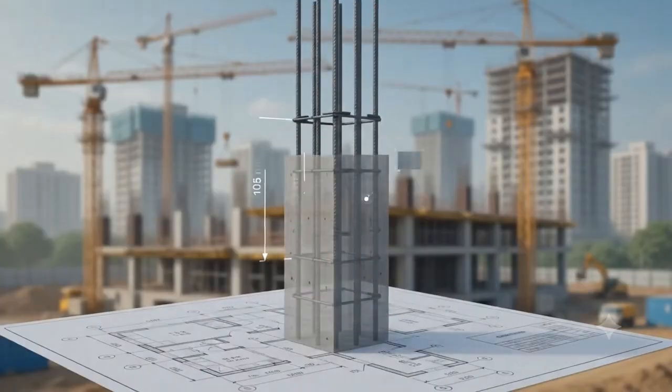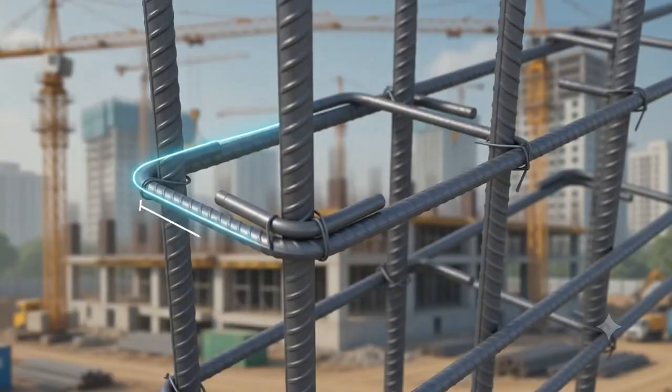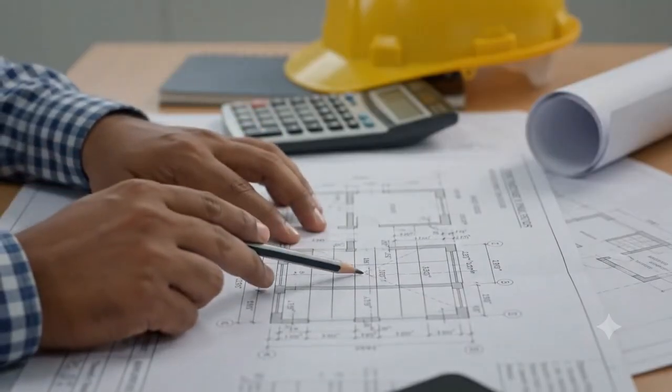Let's calculate steel bars. Step 1: Find the cutting length of main bars. Step 2: Determine the number of bars. Step 3: Find the cutting length of stirrups. Step 4: Calculate total steel quantity. Step 5: Multiply total length by unit weight to obtain the steel weight in kilograms.